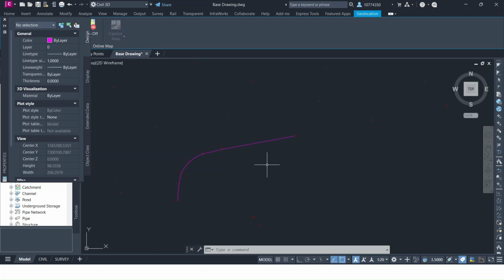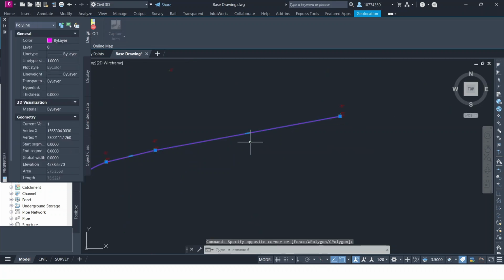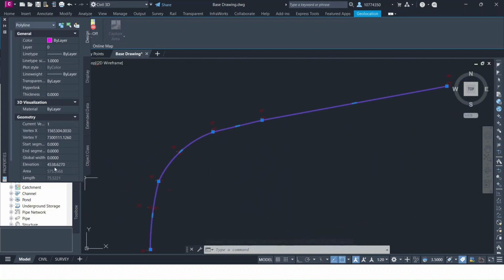It's just going to make it difficult with a surface when you're trying to connect things to a break line, and the break line is at 0 where everything else is at 4,500 and something feet. So you'll create big dips and divots. My advice is make sure these all have an elevation, even if they're all the exact same thing, like this 3862.7.